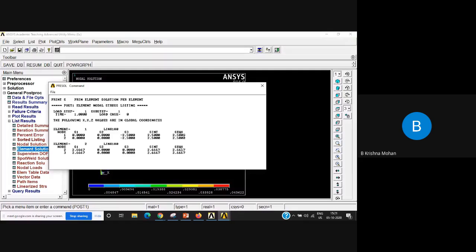So since they are the same, you can't differentiate much. So that's why in the previous plot, in the contour plot, both the elements are represented by red color. Okay, because the values are near to each other. Always remember that in a truss member, stress along the span will remain the same. So that's why the value will be the same here.